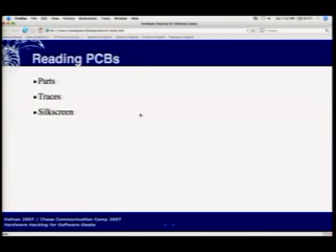Unpopulated pads are also useful. I unfortunately missed Joe Grand's talk, but even just looking at this, I knew that it was doing wireless because it has a pair of antennas on it, these loop tracks.